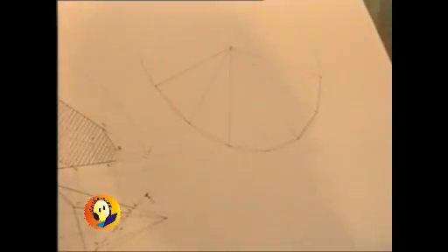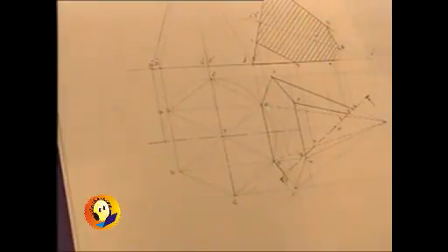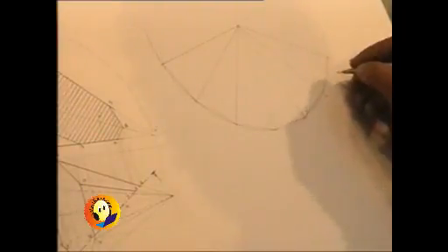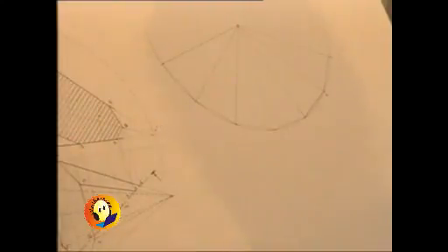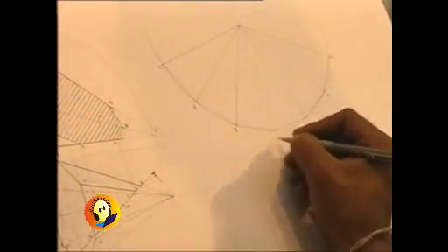You will observe that generators B and C, BV and EV, have been removed fully, and as these 2 generators are removed fully, they should be taking one place, one corner somewhere, and so the naming should go like so. The naming that we will prefer to have over here is, this should be generator B, then generator C, and so this is going to be generator C, D, E, F and A. This is how we will be naming the hexagonal pyramid's development, so that now it will be in continuation.